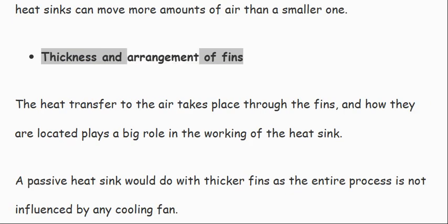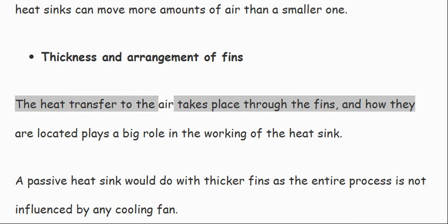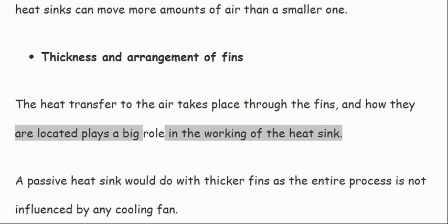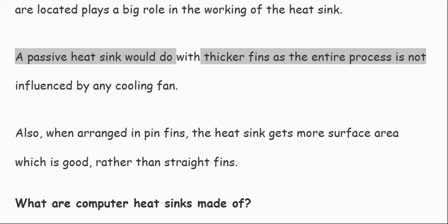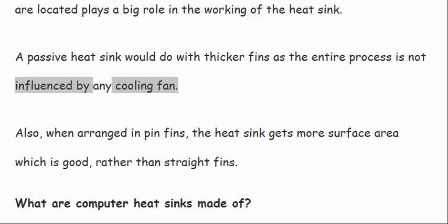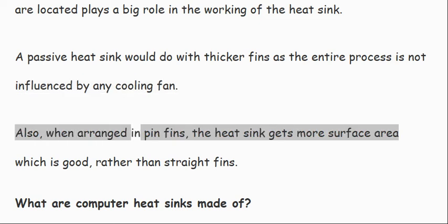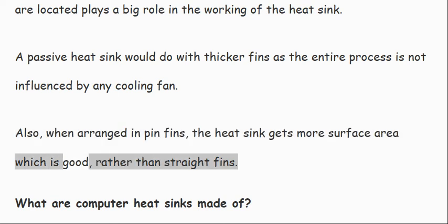Thickness and arrangement of fins. The heat transfer to the air takes place through the fins, and how they are located plays a big role in the working of the heat sink. A passive heat sink would do with thicker fins as the entire process is not influenced by any cooling fan. Also, when arranged in pin fins, the heat sink gets more surface area, which is good, rather than straight fins.